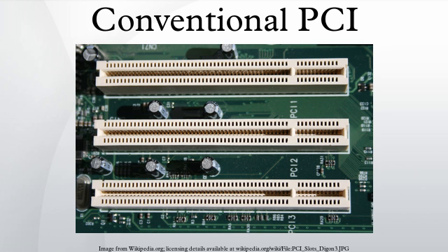Technical details of Mini PCI. Mini PCI cards have a 2 W maximum power consumption, which limits the functionality that can be implemented in this form factor. They also are required to support the CLKRUN PCI signal used to start and stop the PCI clock for power management purposes. There are three card form factors, Type I, Type II, and Type III cards.